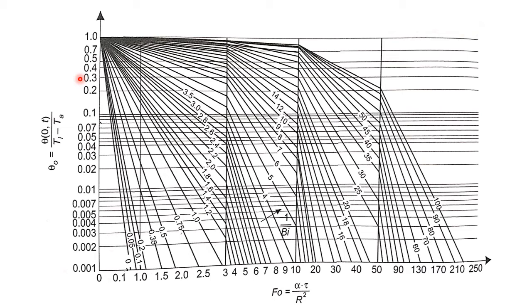So already we have calculated 1 divided by Biot number as 0.854. This is the line for 0.75, and the 1 divided by Biot number line is 1. So 0.85 will lie somewhere in between here, and I will draw a straight line with the help of a scale till the end of this graph.